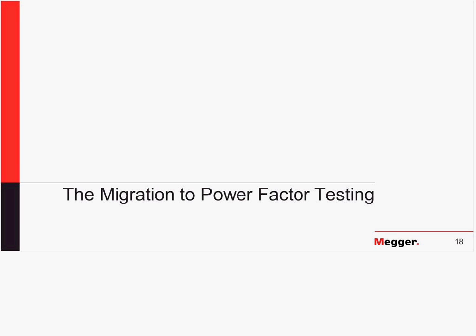So depending on what frequency we're operating at is going to definitely influence which polarization processes are having time to contribute to the measurement, and which ones are not. So it is a phenomenon that's relevant to this discussion about AC testing, not just DC testing.